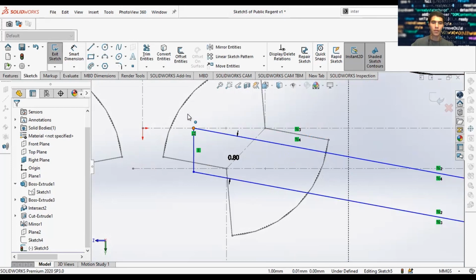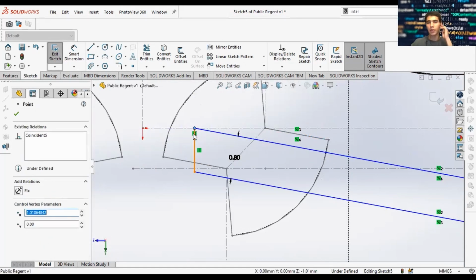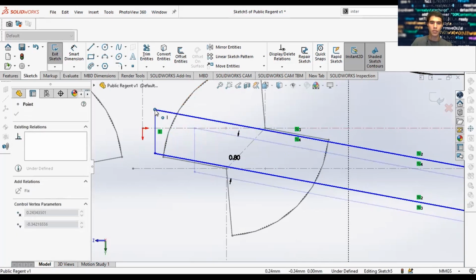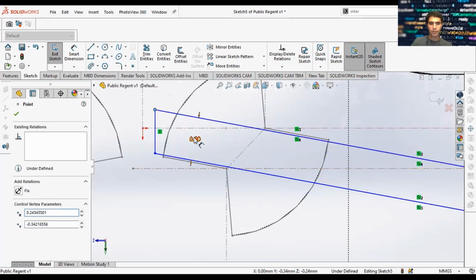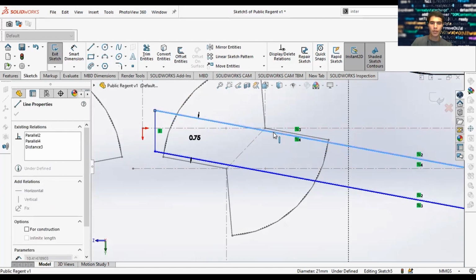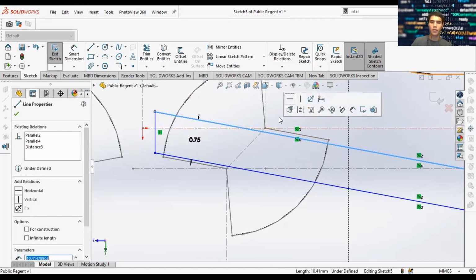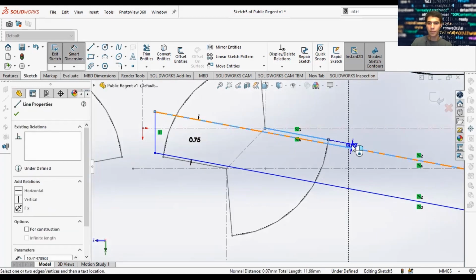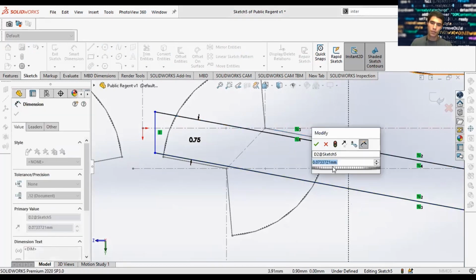Yes. Okay. So right now what is limiting our sketch, if you see it, is this coincident constraint. So we'll go ahead and remove this, and this will allow us to drag our sketch. So we want to drag our sketch upward here, in between these two conditions. We'll put it centered between our hinges. We have one hinge here and our other hinge here. So what is the dimension here? 0.07.